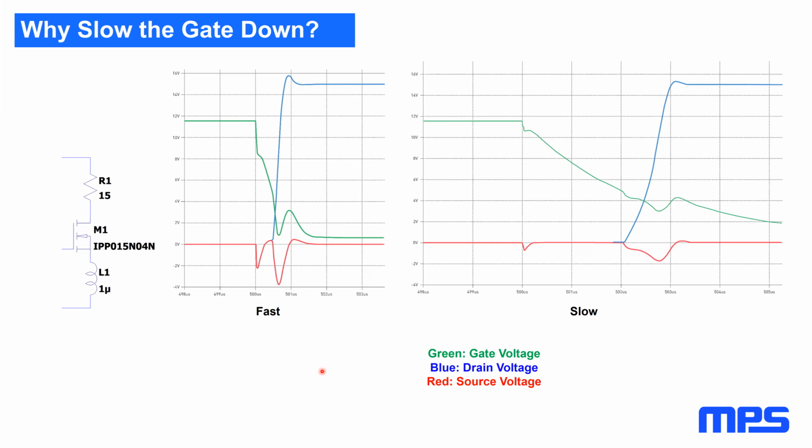Okay, and then we've got, can you discuss MOSFET safe operating area, SOA, and how it influences gate driver selection? Good question. I'm trying to think of whether SOA really affects the gate drive. I mean, SOA basically only applies during the transition, right? When the MOSFET is switching.